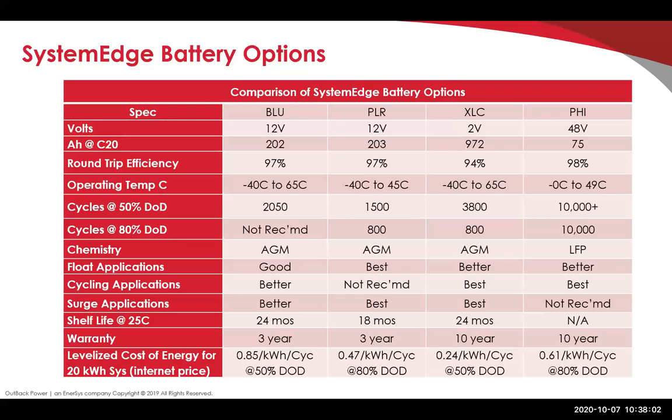Some of the lithium iron phosphate batteries I've seen have what some people refer to as a dumb BMS. It doesn't interact with anything outside its system. It just looks at itself, and they're designed to operate like an AGM battery. So I don't know if that's a long answer to the question.